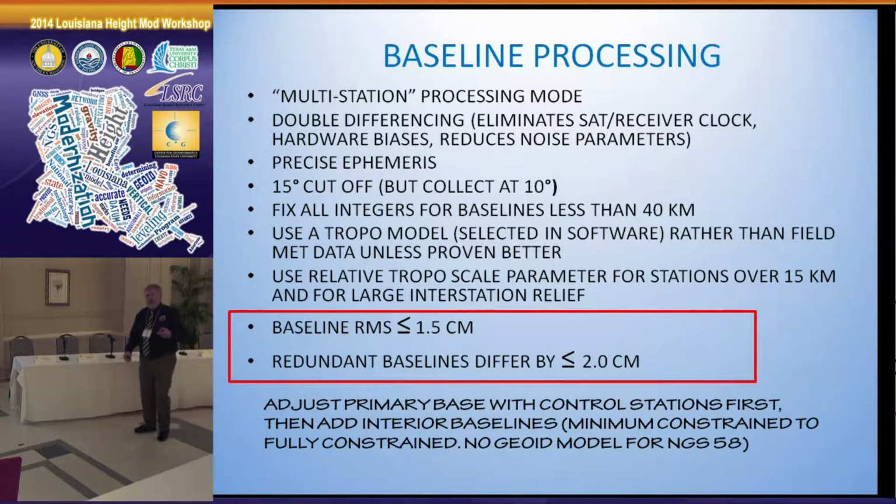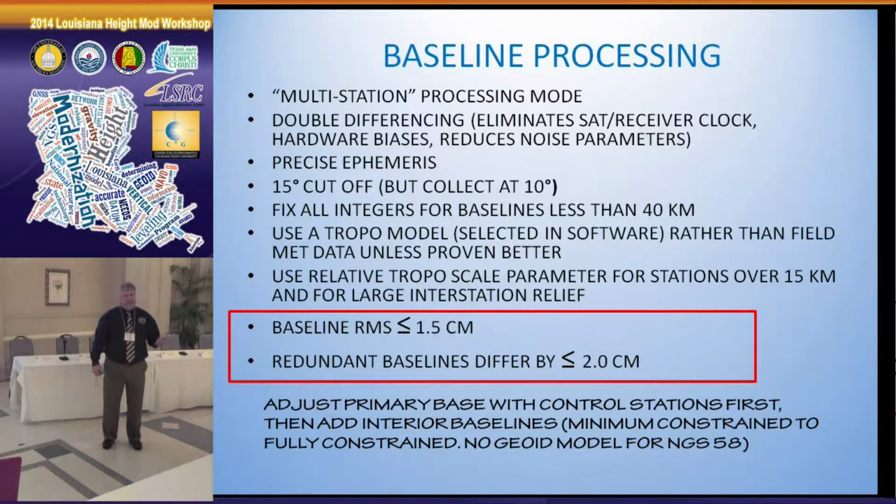Well, pragmatically now, you can use the rapid orbits, which you can get 14 hours later, 10 hours later. And they're almost just as good. So these guidelines, at that time, were correct, because I saw a lot of differences with the broadcast. What you do is an error check after each day. You process the data and there are no blunders. Then, later when you get the precise, you reprocess and get a final answer.